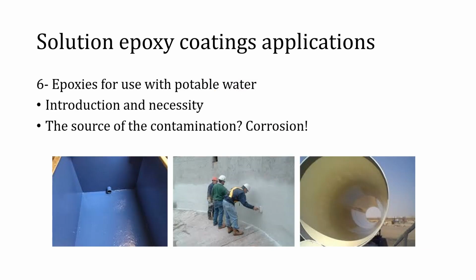Water supply and storage systems are vulnerable to contamination. The source of this contamination could be corrosion, either in reinforcing steel in concrete tanks, steel tanks, or in the cast iron pipes, which happens in the municipal water supply pipes. The corrosion is also much more severe in this system, as here bleaching powder might be used to disinfect water, which emits chlorine in the form of chloride ions. This chloride promotes the corrosion process via an electrochemical reaction.